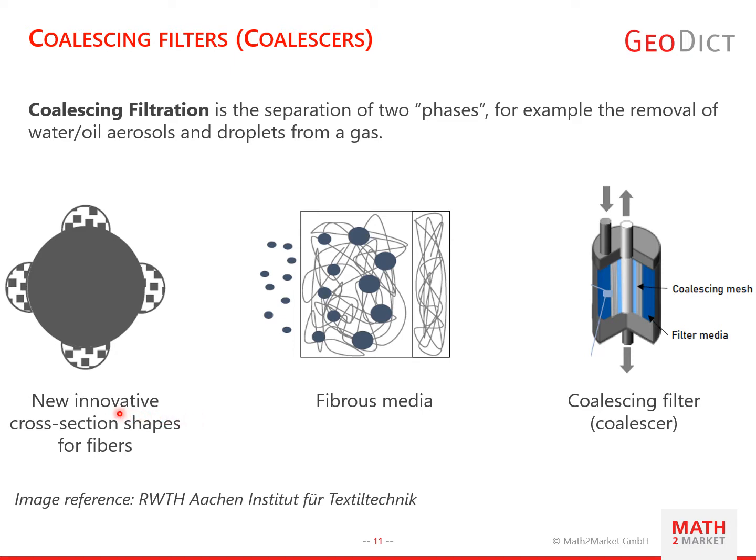As you can schematically observe in the middle image, when, let's say, aerosols are injected into the media from the left side, and more aerosols are filtered, the coalescence will occur among the aerosols contacting each other. And when the size and the corresponding mass of a coalesced droplet increases, then this droplet may be detached and discharged from the media as soon as the gravitation force becomes larger than the adhesive forces between droplet and fiber.